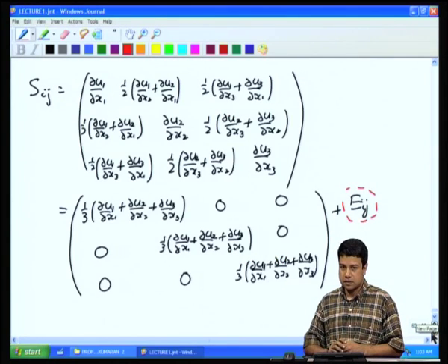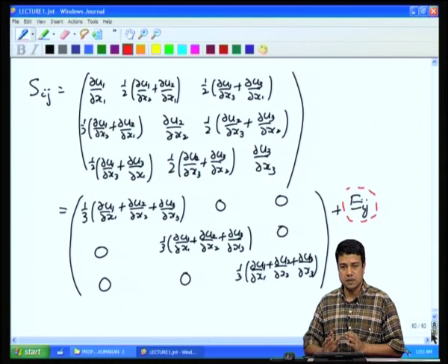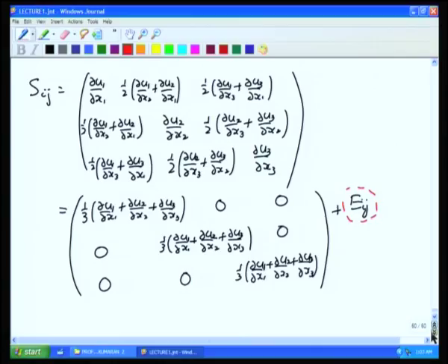Why did I do this? Because each of these matrices represents a different type of deformation. We will discuss in the next lecture what types of deformations these represent. These types of deformations are independent of the underlying coordinate system that you are using to analyze the problem. So, if I separate this rate of deformation tensor into these 3 different matrices, these types of deformation will be independent of the coordinate system used, even though the individual components of this rate of deformation tensor may depend upon the components used.